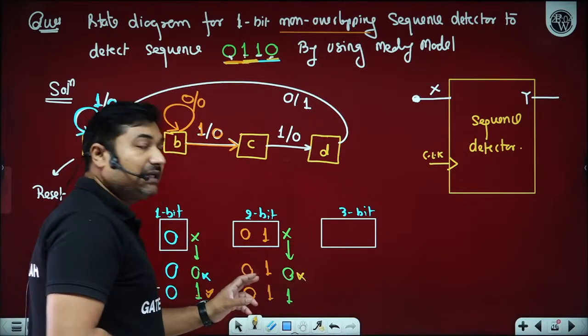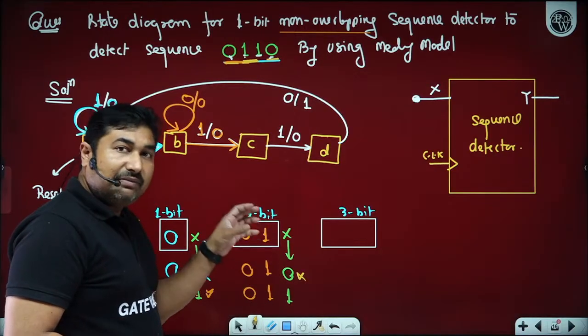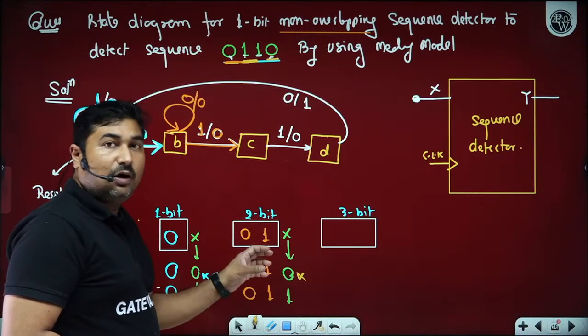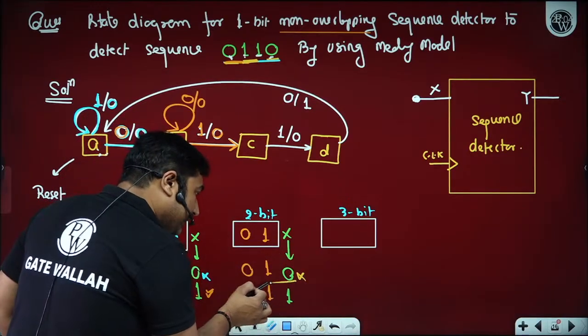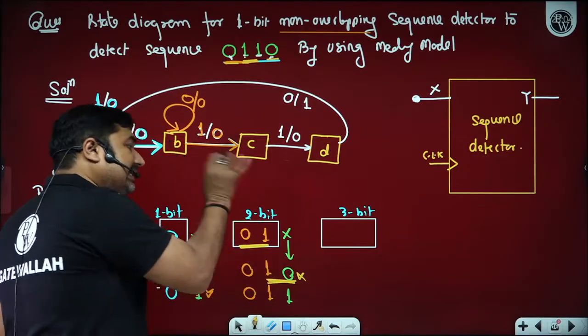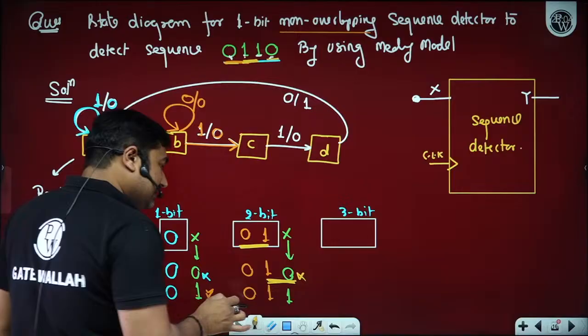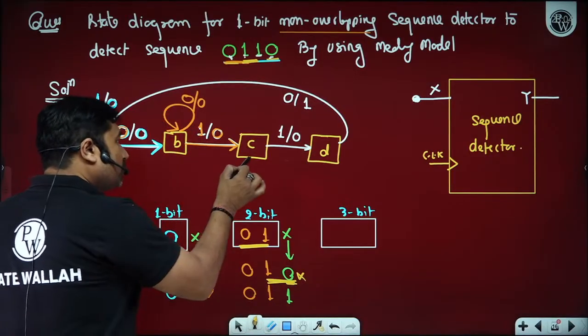Under such a condition, either it will remain in state C or it goes back to the previous states. That we can check with the last 2 bits. Compare the last 2 bits with the 2 bit state. If it matches, remain in state C. Otherwise, compare the last 1 bit with the 1 bit state. If it matches, go back to that state.